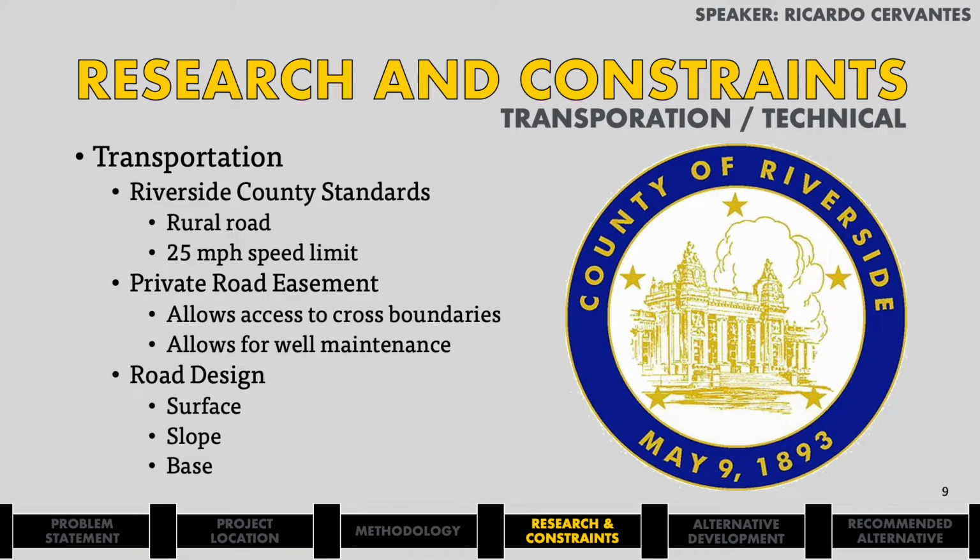The surface grade we will be using is impermeable asphalt, which is most commonly used road material throughout the U.S. Going down the list, we have our final grade, then have our base of small aggregate such as silica sand and gravel pieces. Through extensive research, we follow regulations for a slope of the road of 2%, or a quarter inch of fall per horizontal foot of the road width. Our water resource team will now expand on their research.